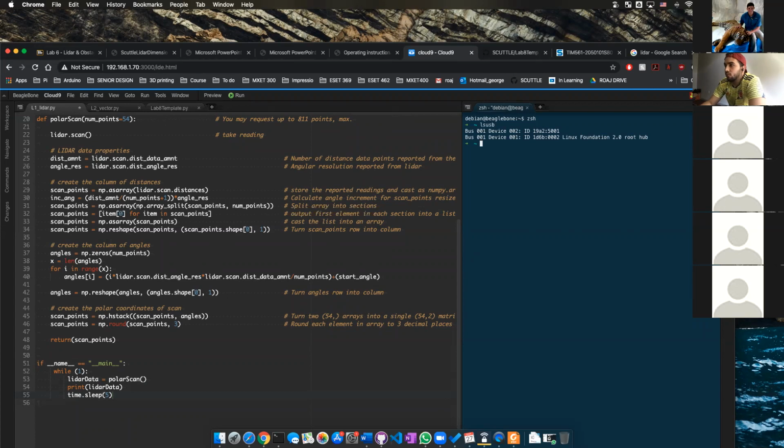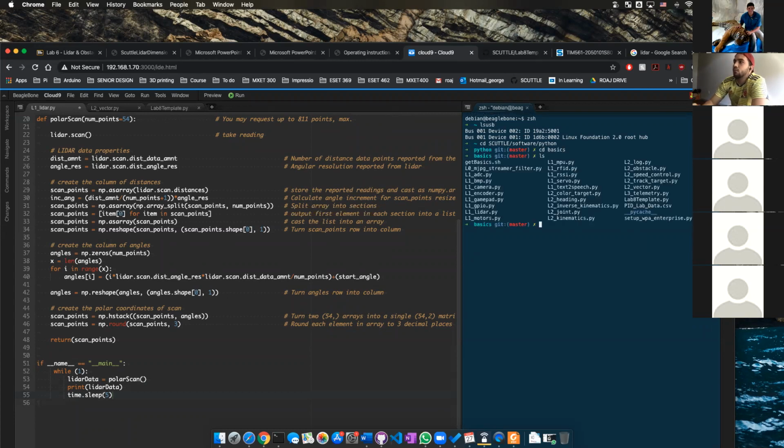You can do a couple things. In your code, you can measure that as I go through this array, if I'm passing over a wall, which has basically a straight line, the points are within a certain distance from each other. And so I can assume, okay, this is mostly a straight line, or I can do like a best fit line type of thing from a certain section of the map to another section of the map.